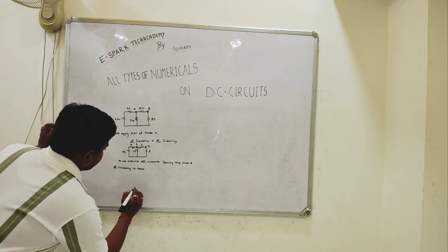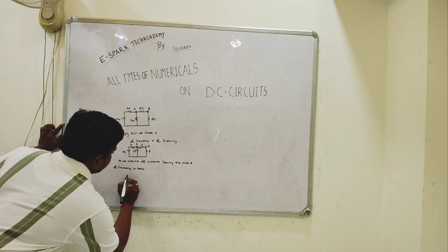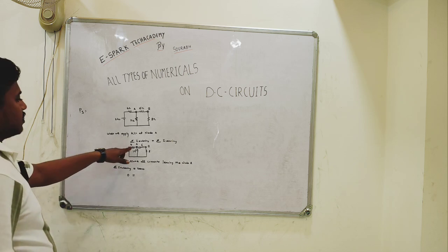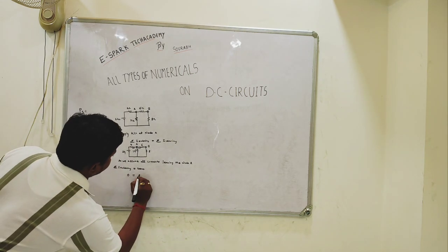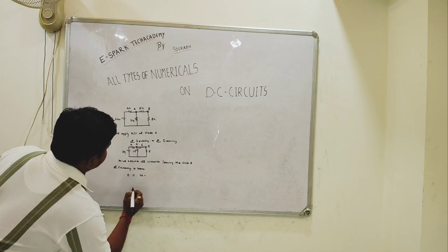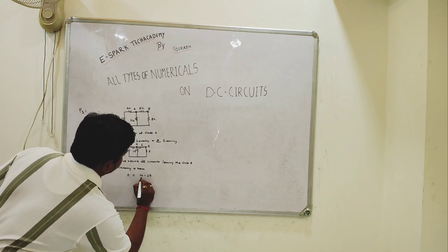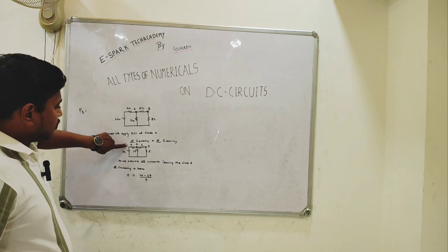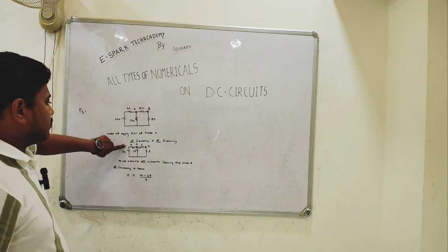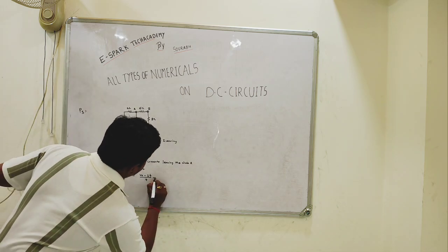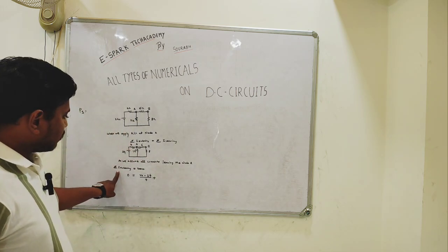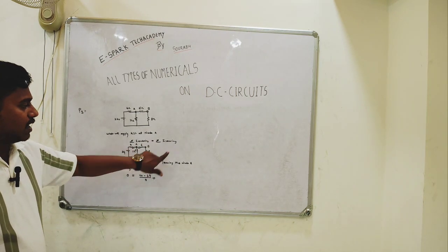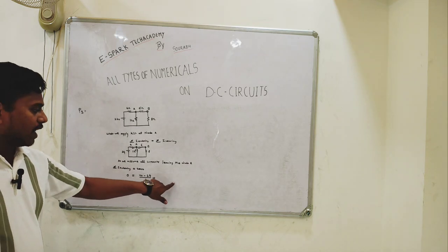Hence 0 is equal to the leaving current. First current will be VA minus 24 divided by 4 for 4 ohm limb. You can say limb or element. Now plus, now what we are doing, as summation of entering is 0, that's why I have showed here 0. Now summation of I leaving, all these currents are leaving, hence we are adding them.